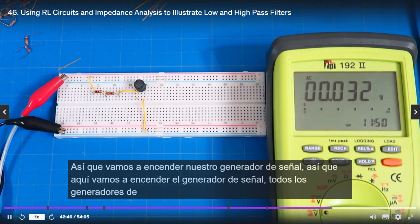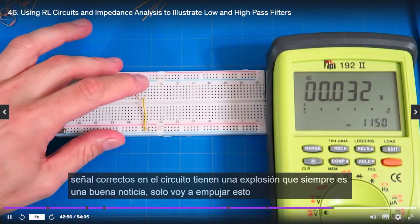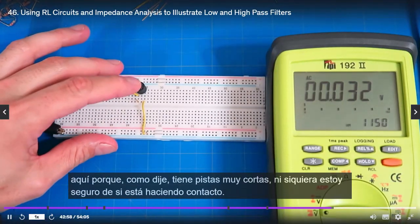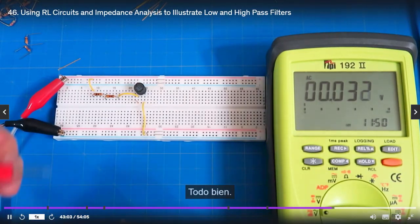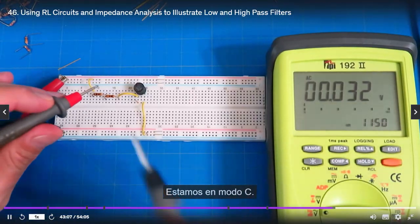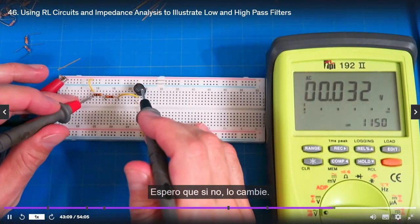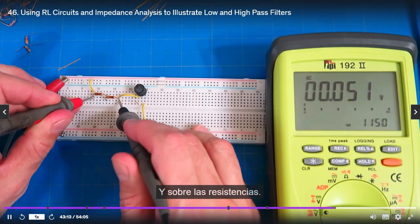All right, we're going to turn on our signal generator. Here we go. Signal generator's on, and the circuit hasn't exploded. That's always good news. I'm just going to push this in here because, like I said, it's got very short leads. I'm not even sure it's making contact. First, let's measure the voltage over the resistors. We're in AC mode. We got the right range here, hopefully, if not, I'll switch it around.